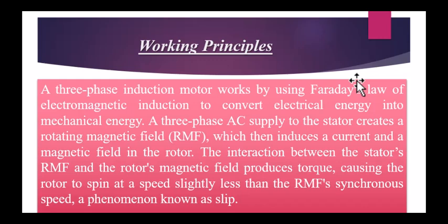This is the most common question that can be asked of you at the time of an interview: what is slip? If you answer in just one statement, that the difference between the rotor magnetic field and the stator magnetic field speeds is known as the slip of the motor, then your answer will be correct.